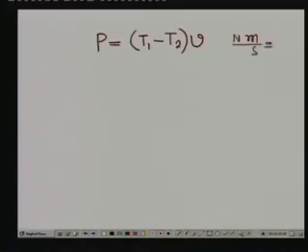So, this is effectively the watt or power. So, T1 minus T2 into V is the power. Here, this power is actually your design power, okay, that you understand by multiplying by service factor. Now, out of this, if we can replace T1 by some means, then our problem is solved.